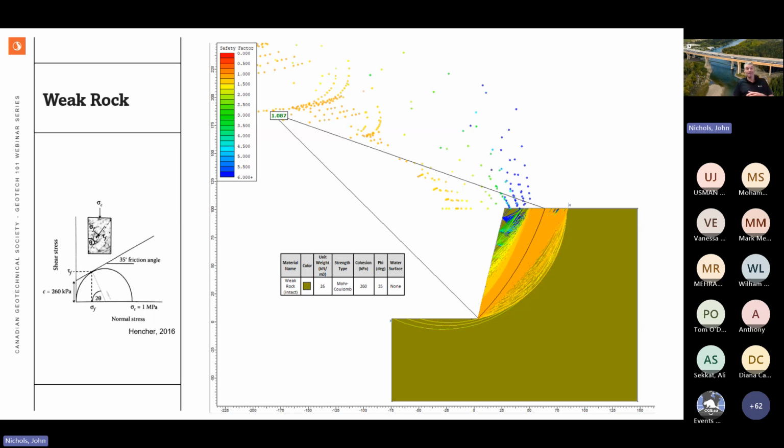So maybe some engineers would think, oh, that's how rock is, it's just really strong. But the major flaw in this analysis is that most rock masses, even cemented overconsolidated soils or partially cemented soils, contain natural discontinuities or flaws in the rock. And these discontinuities are where rock engineers make their money. They live there, and they must be considered. So this is the major difference: rock engineers seek to capture the condition of these natural discontinuities in the rock mass.